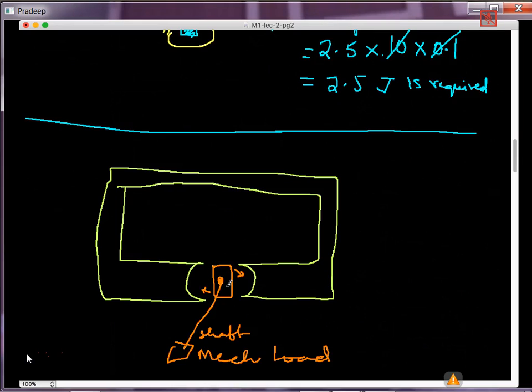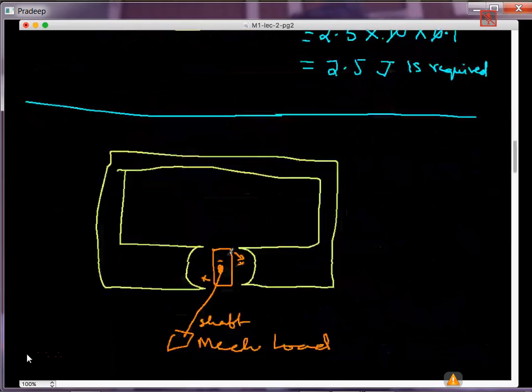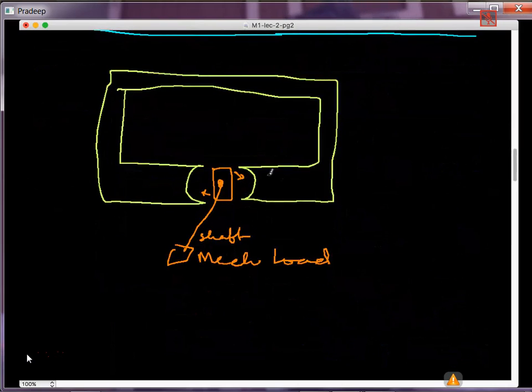And whenever you reduce the air gap in a machine, more energy is stored in the magnetic field and more mechanical output you can get. So the whole idea is to reduce the air gap between the magnetic field so that the reluctance is reduced. So earlier example is a linear motion, whereas this example is a circular motion. So this is like the field and this is the armature, and in the armature you can rotate it. So we'll see more details about the machines in future. So any doubts so far in this lecture?